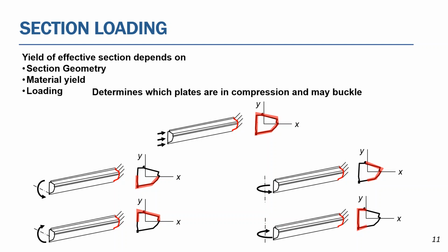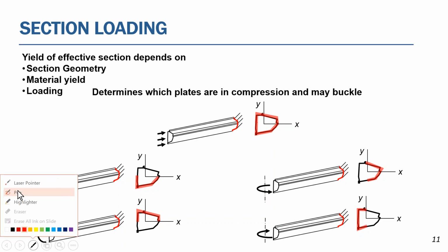For example, if we have a long flange and we put the spot weld at the very bottom of the flange, the buckling stress of that long unsupported piece will tend to buckle at a lower load.